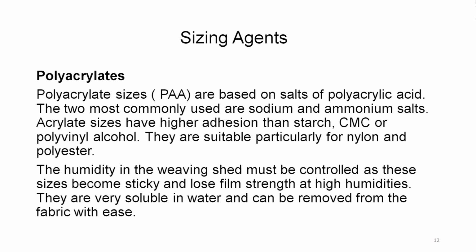Polyacrylate sizes, that is PAA, are based on salts of polyacrylic acid. The two most commonly used are sodium and ammonium salts. Acrylate sizes have higher adhesion than starch, CMC or polyvinyl alcohol. They are suitable particularly for nylon and polyester.